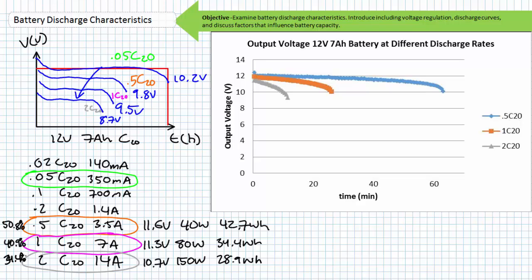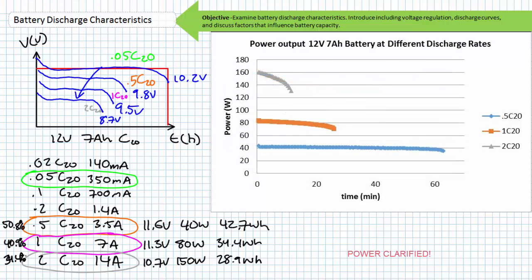This goes to show you that the nominal capacity of a battery is a moving target, and the amount of energy capable of being extracted from a battery is a function of how rapidly the chosen application discharges it. Be aware the power curves for these 3 different discharge rates for the same battery will be slightly different than the voltage curves when placed on the same graph.